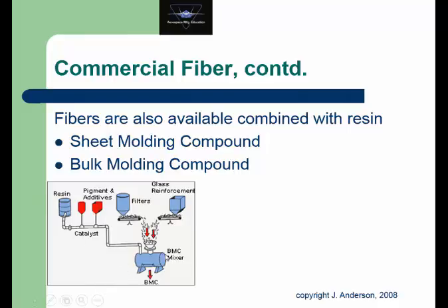Now there's some things to consider here. This shear mixer is a pretty sophisticated piece of equipment, although it's sort of a blunt force instrument too. As you add shear in here to mix all of this stuff together, you're also adding heat into the mixture because of the friction that you're creating as you mix this.